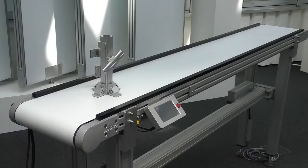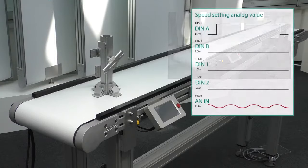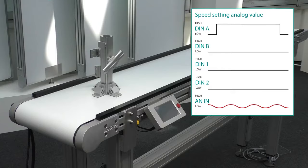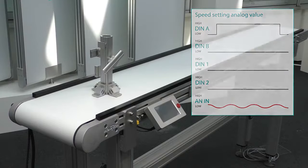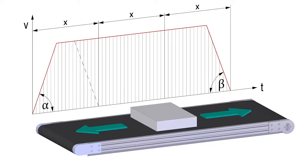The speed setting via an analog set point from 0 to 10 volts is possible in both transport directions. To change the direction of rotation, simply change the signal of the DIN A and DIN B digital inputs. For positioning, the conveyor must be stopped and brought into a braked state. Set the digital inputs DIN A and DIN B to high. Use the digital input DIN 1 to set the direction of transport.